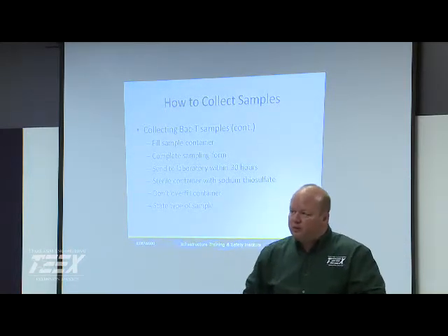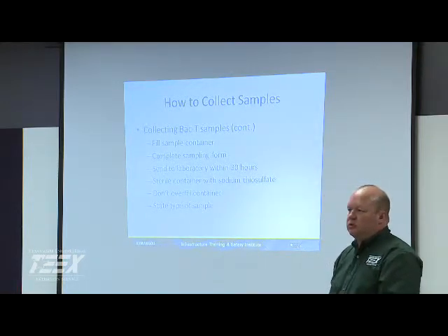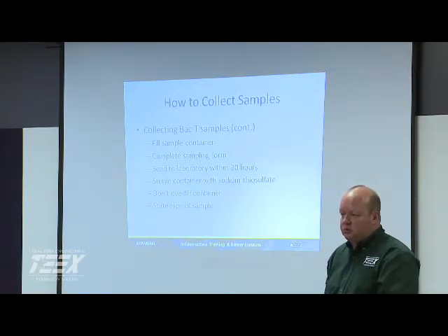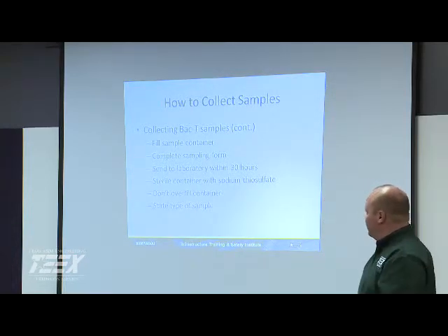So that changed, because we were allowing systems to code line repairs and customer complaints as special samples, and they wouldn't count towards the monthly compliance number. They came in and said, no, if it's water being used by the customer, then it's got to be a compliant sample, so it's got to be considered a distribution sample. I'll have to ask somebody in the lab in San Antonio about that.